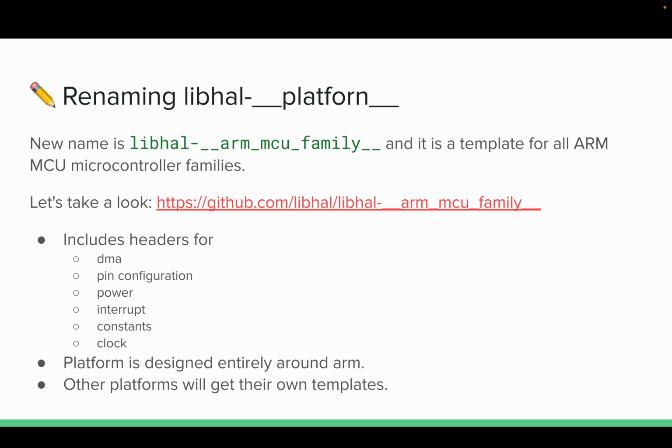The design choice that I have for this is that the DMA handler should basically iterate through the blocks until the entire thing's finished, just so that the logic can be centralized in one spot and not have to be redistributed everywhere else. If we had to ensure that the length of the whole transaction was less than the maximum amount the DMA can handle, for example, for LPC, I think it was, maybe it's this, I forget, or maybe this was for LPC. I don't remember off the top of my head, but let's say it's like 4K.